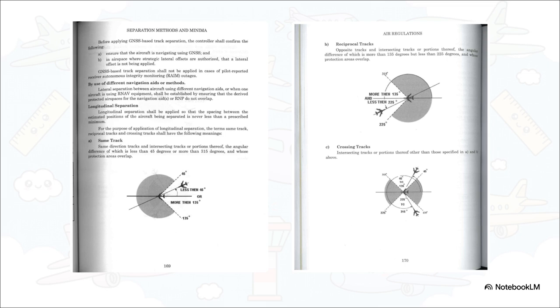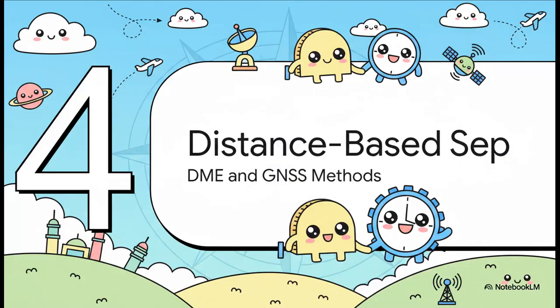So what's the rule? Where lateral separation is not provided, vertical separation must be provided for at least 10 minutes prior to and 10 minutes after the estimated time of passing. You really do not mess around with head-on traffic. 10 minutes before, 10 minutes after. Period. Next up, Section 4, distance-based separation methods.